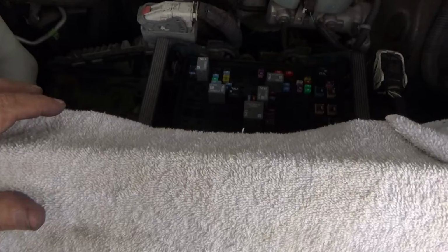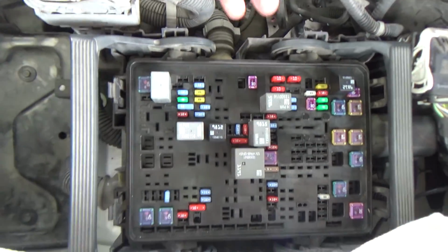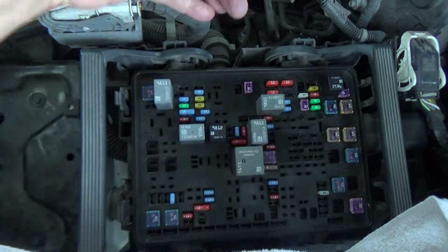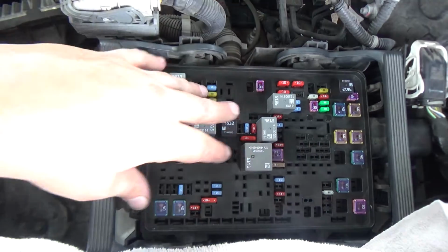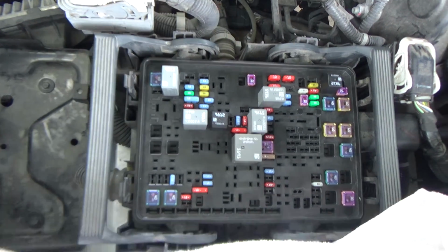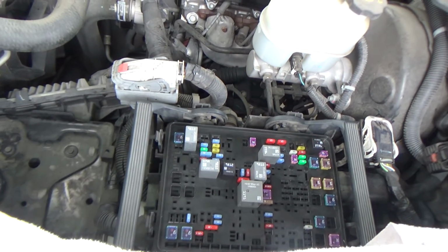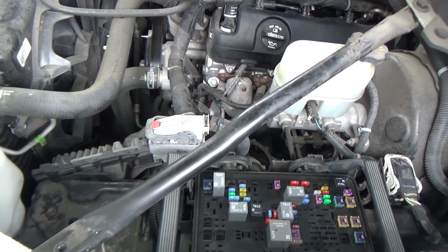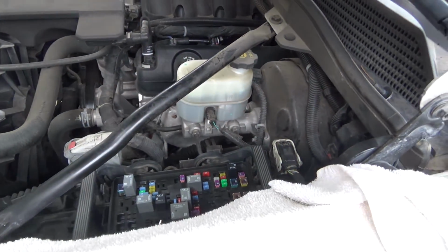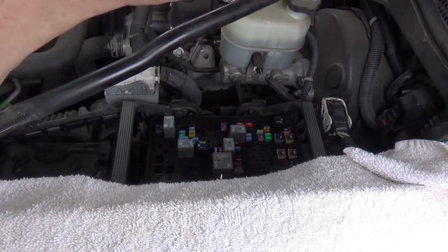Snap the cover back on it. Make sure your rubber seal is in the cover. They put a rubber seal up top here so water can't go down from the top and get into it, but the bottom is completely unsealed. That's the downfall of these things. So, anyway, we're done. That looks like it took care of it. Just got to put this back on and then put the cover on. Anyway, 2016 GMC Sierra, replacing the internal printed circuit board relay for the high-speed wiper.